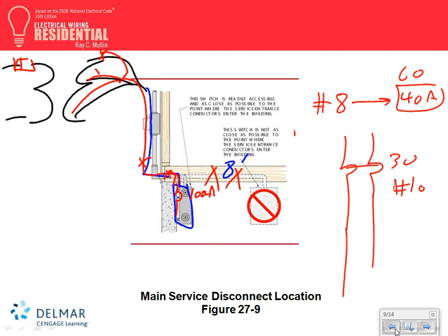30 on a building? Well, right here it says one circuit installation. In a 2 circuit installation. Right. So my point is, on this 30 amp special installation, you could have gone with 10. You can't now because the minimum service conductor you can bring is what? Number 8. Number 8.